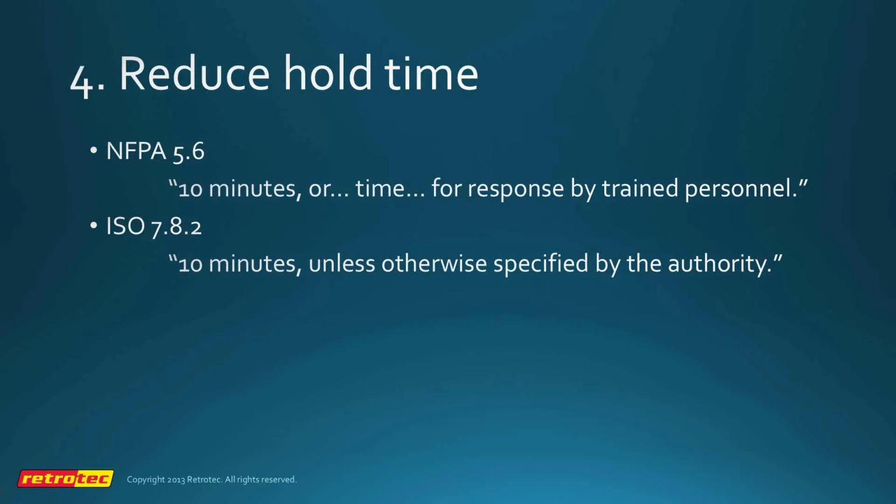And I suggest for small enclosures of 250 square feet or under, 25 square meters or under, that we consider a hold time different than 10 minutes. So by the time we get down to about 100 square feet of floor area, it becomes very, very difficult to get a 10-minute retention time, and in a lot of cases a 5-minute retention time is sufficient.